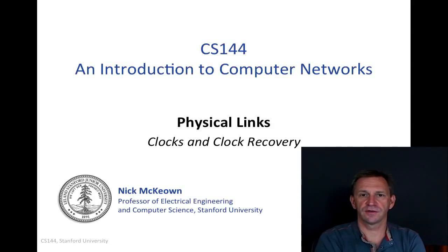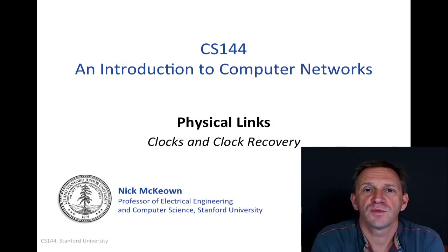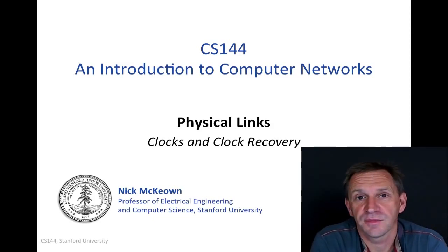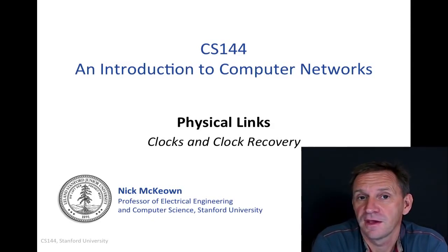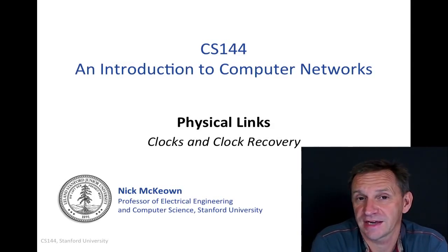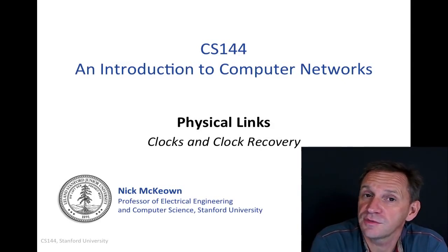In the next two videos, I'm going to be telling you about clocks and clock recovery. Whenever we send data over a link, for example an Ethernet link, we normally assume a data rate, like 10 megabits per second or a gigabit per second. When we send at 10 megabits per second, we're assuming that each bit lasts 100 nanoseconds, or 10 million of them per second. And at a gigabit per second, we're assuming each bit lasts a nanosecond.